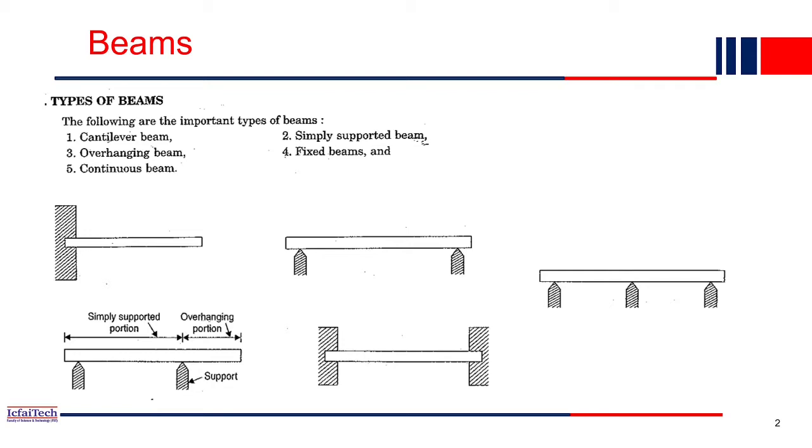So in that case, it is very difficult to draw the bending moment and shear force diagram by hand. So for that we need a computer program. Here I will demonstrate with a simple code how to write code in Matlab to compute the bending moment and shear force.